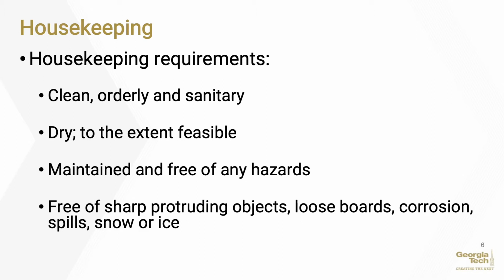Slips can be caused from grease, oil, wet paint, water, or other slippery contaminants on floor, spills, or debris. Trips can be caused from poor housekeeping, clutter, loose cords, improper use of floor hole protection covers, power cords, construction materials, or other items in the work area that create a tripping hazard.